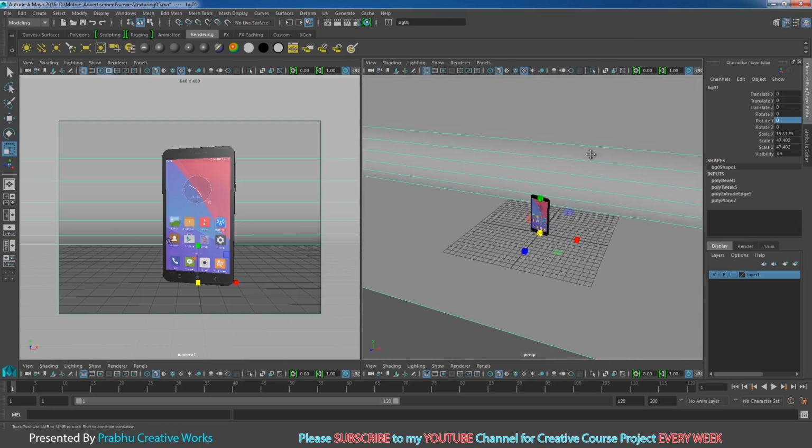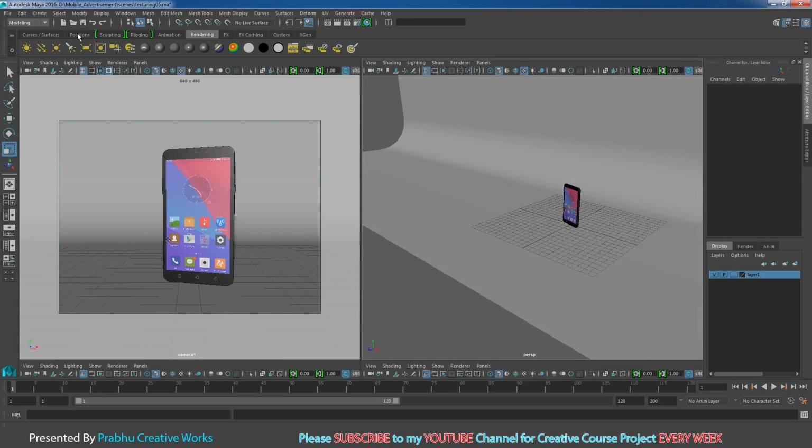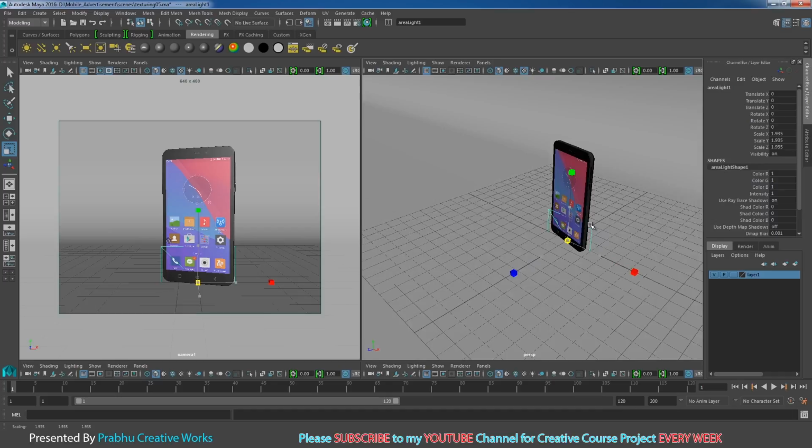Now we want to make lighting for our scene. So go to rendering and click on area light over here. It will automatically be created in the center of the grid. Press R and scale.